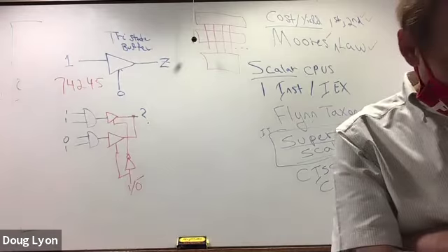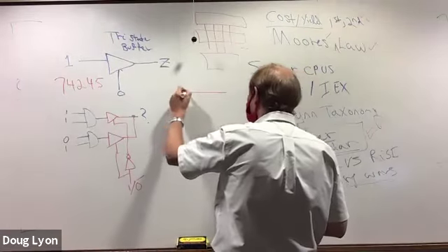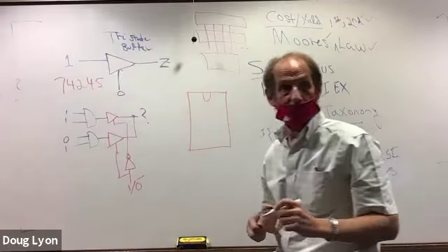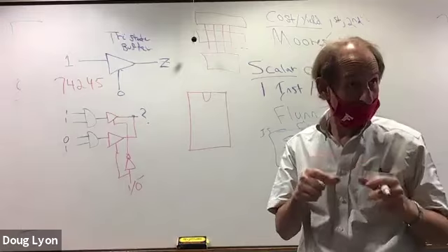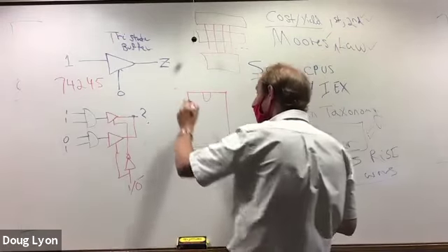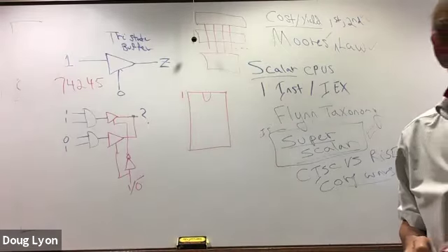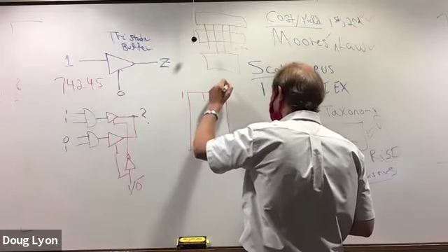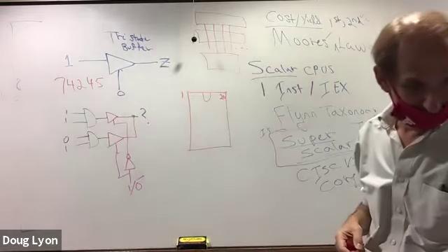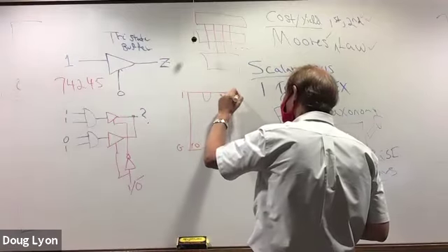As a practical matter, when you find these things for your little breadboards, when you want to build stuff, real hardware, you'll see there's a little notch that gives you an orientation. That makes this pin 1. Moreover, and you've got to use the data sheet, you'll find that the ground and the VCC are at different locations. So this would be like pin 20. And this might be, I forget how many pins it is, 10, yes? And that would be your ground, and that would be your VCC.